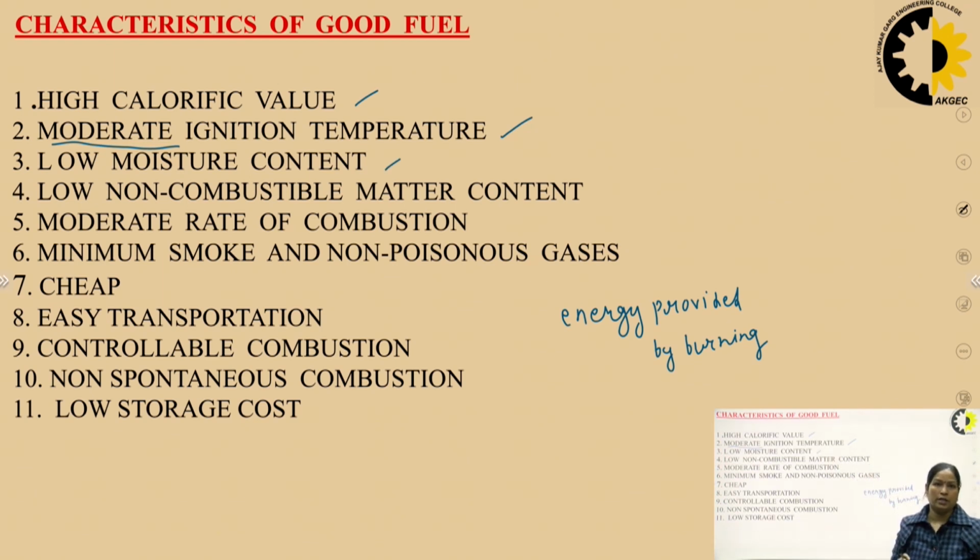Another important point is low moisture content. If there is a huge amount of moisture in the fuel, the weight of the fuel increases and it decreases the efficiency of the fuel, because moisture is not going to burn at all. H2O cannot react with oxygen further and form a combustible product. So moisture increases the weight of the fuel, but it does not provide any efficiency or any calorific value to the fuel.